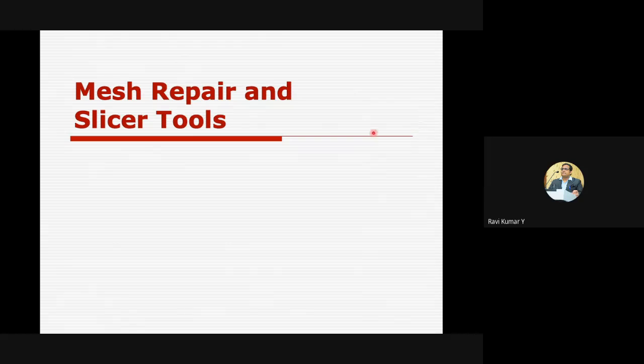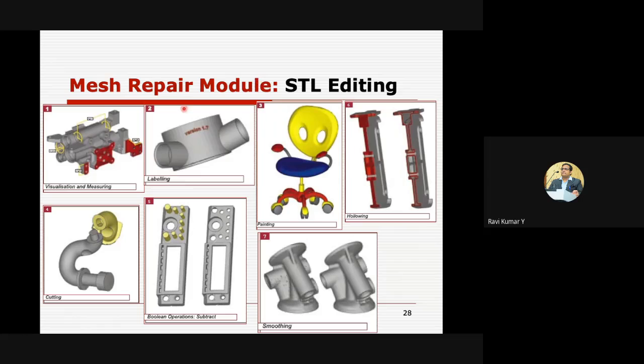And then last class we also discussed some STL file problems, right? So the mesh repair and the slicer tools: you may use some STL editing tools, maybe MeshMixer or MeshLab or Magics. You have plenty of tools to do this mesh repair, for visualization, measuring, labeling, painting, healing, cutting, Boolean operations, or smoothing of your STL files.